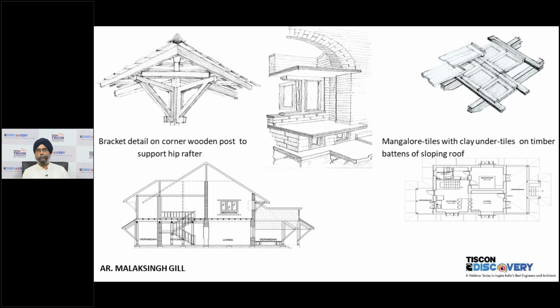You see a construction of a bay window in this house. You will see that below the seat there is an opening in the bay window. That opening actually takes air in when the windows are also shut. Suppose in the monsoon the windows are shut, your house will not become stuffy, because these windows below the seat can be operated by your foot. They are pivoted windows, and you can have the cool breeze coming into the house.